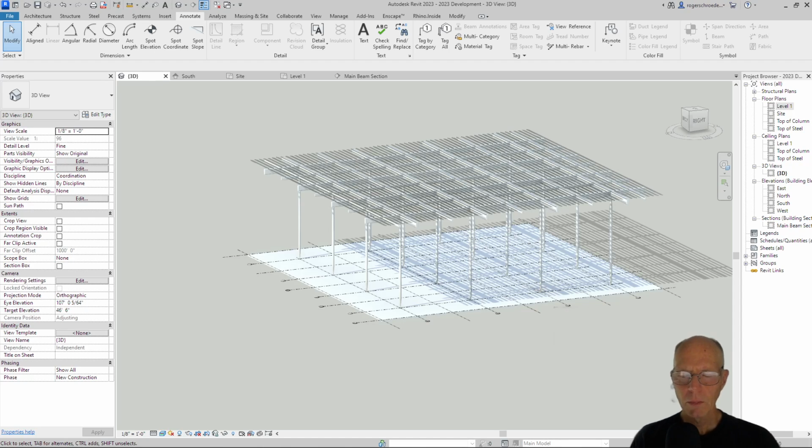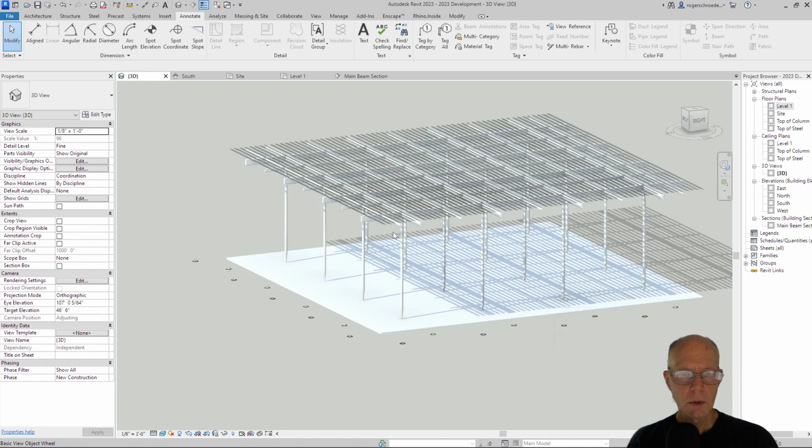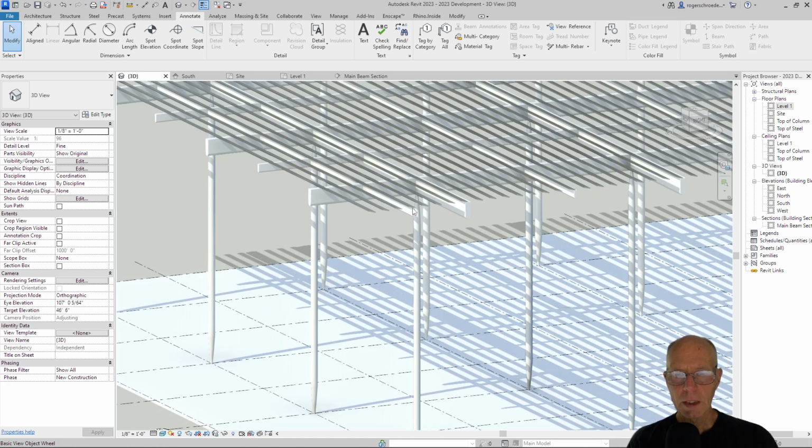So with most types of structural analysis, the first thing to do is pick the worst case scenario. I mean, the worst loaded condition, and that's really the end conditions of these, where if I zoom in here, the column or the beam over that last column is really cantilevered out, supporting all these loads coming out this way. So this beam has to carry the most amount of load.